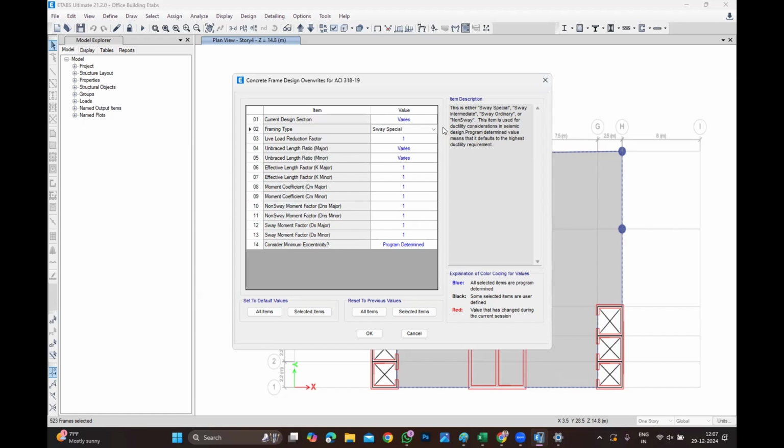Planting, right? You are planting trees. How do you plant the trees? Like roots, right? That's how you are planting the columns, like an L bar. If you are taking the columns in the wall, either in a shear wall or a retaining wall, are you going to take the rebar till the foundation? Imagine till the fourth floor I have a shear wall. From the fourth floor onwards, the column is going to start. It's not a necessity; I can use the same rebar. Even you can plant new rebar, right?